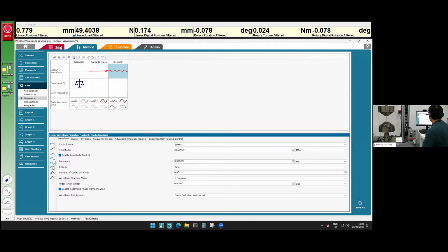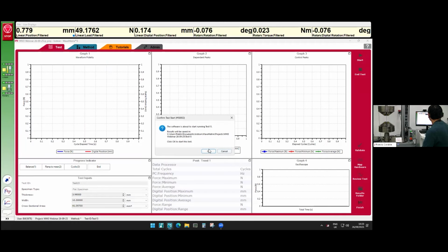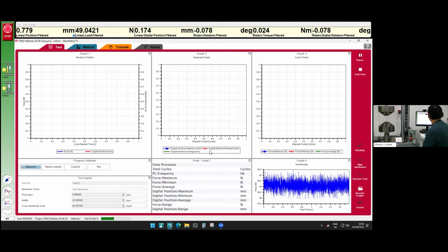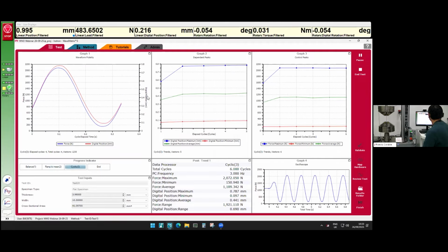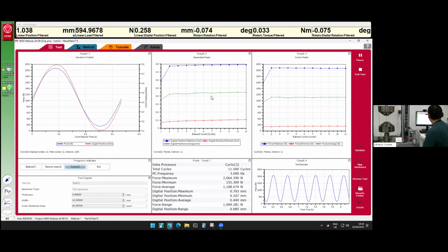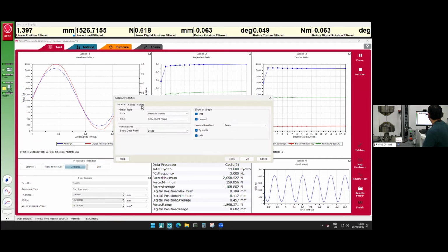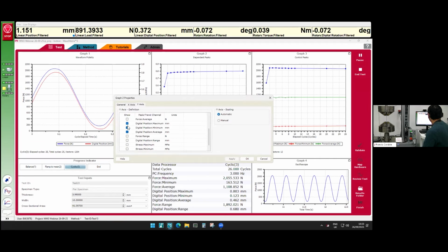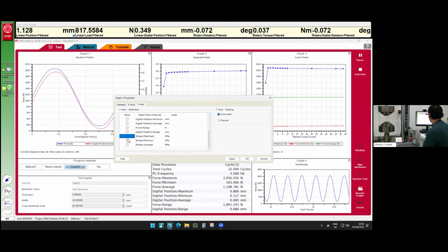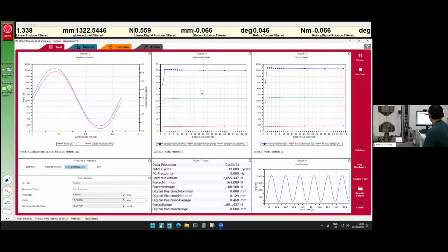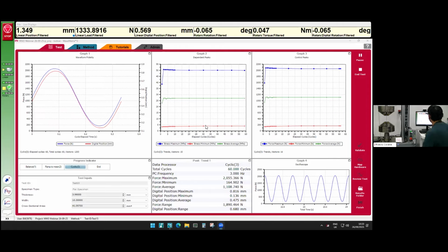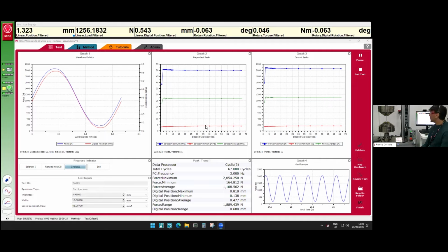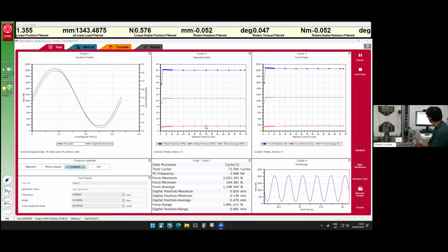So now, when I run this test, I'm actually going to be doing it in the stress control. So I can readjust my layout here, so I can use a graph. So instead of looking at displacement, I could look at stress. Okay, and you can see here we're asking for 50 MPa down to 4, and it's holding steady. So by just doing a couple of tweaks there, we now have a stress control test.